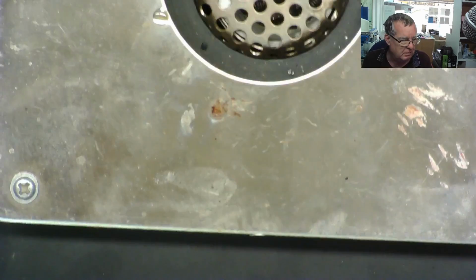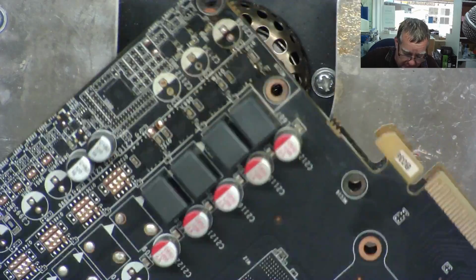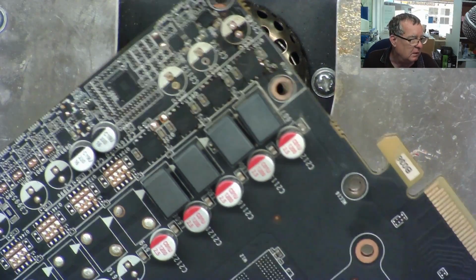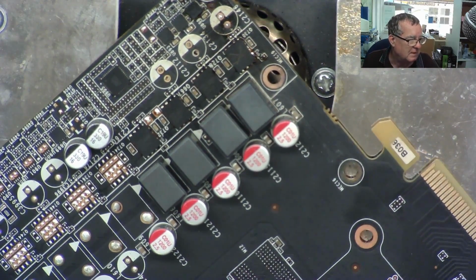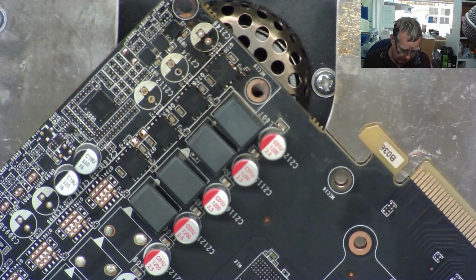So this should answer your question, well, can I just remove the coils or the MOSFETs until the short goes away? And the answer is yes, but do you really want to? Okay, so we'll get over here again and let's have another go at removing this driver chip.